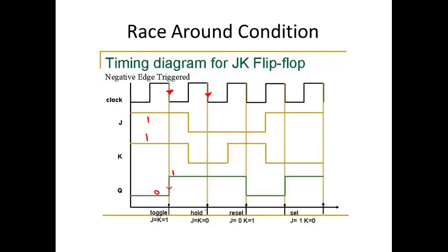this state is over, though the input is 1 at this stage, till this stage it is 1. Only during the next consecutive negative edge trigger, whatever may be the input now, it will sense what your JK input is.